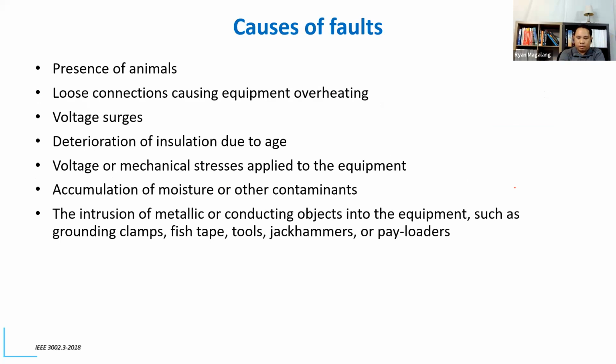This can happen in a substation. That's why in a substation you'll see we put some insulators and some kind of spacer to prevent animals from jumping from insulators to conductors. Then voltage surges, and deterioration of insulation due to age.